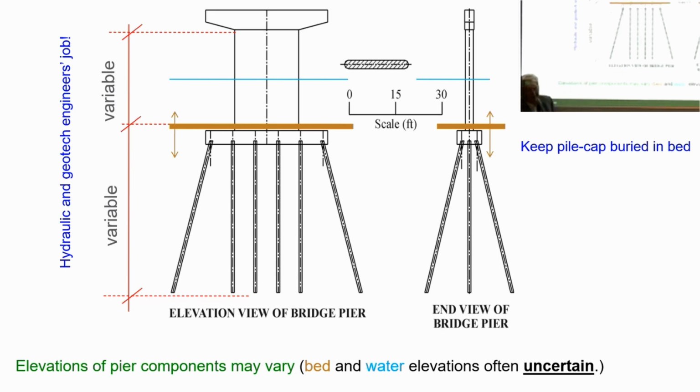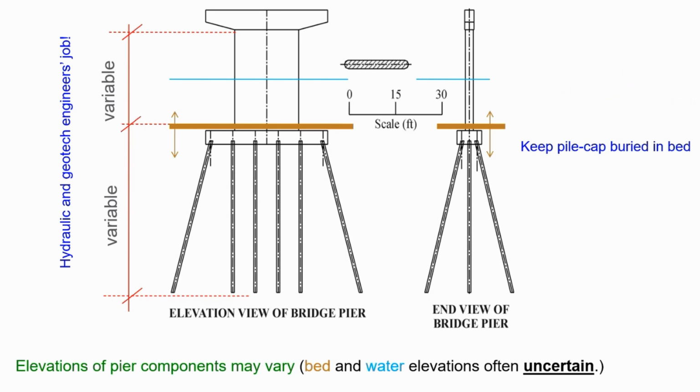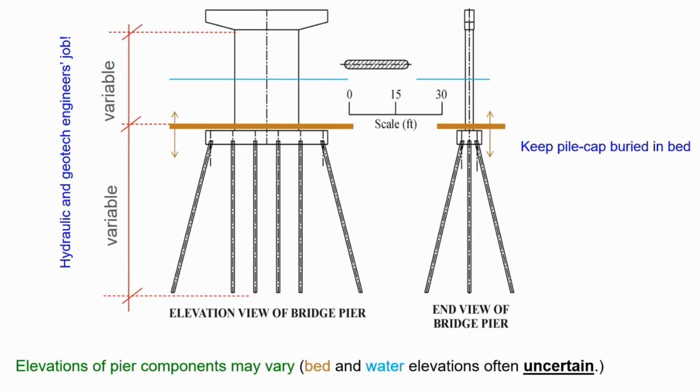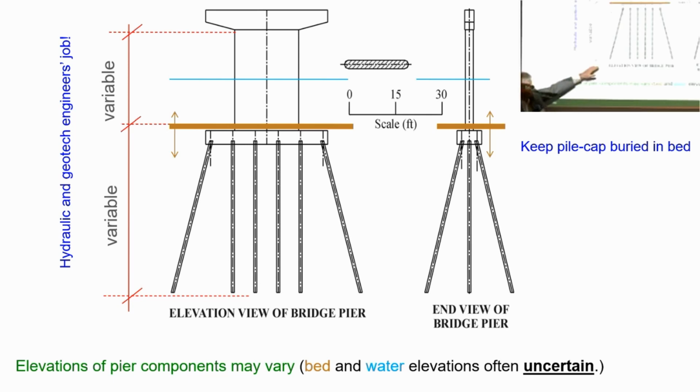If you remember from your geomechanics courses, there are two types of foundations typically. You have a footing, which takes all the load, or you have a friction-bearing pile where the friction up the pile resists the load. So you need to figure out how long these would be, and scour has to be accommodated within the length. These are raked at some angle if there's some lateral loading, particularly through debris or flow drag on the pier. So your job is typically to figure out how high the deck is and how long the piles should be, friction-bearing piles. In Nebraska, generally, road bridges are too low, in my opinion, as I'll explain in my next talk.